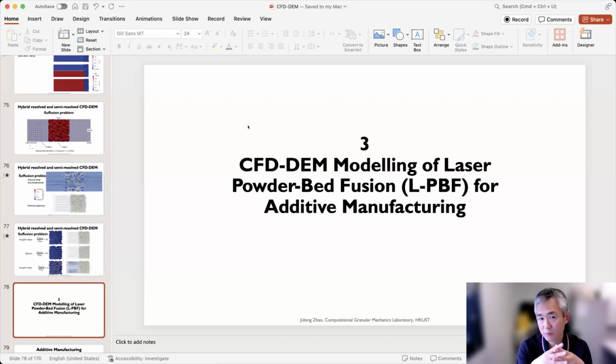You have other effects, and so that is structure response. Of course, as I mentioned at the beginning, this is a simplified way to simulate this twisted wire, and you can further develop or refine this model to capture so-called progressive failure. But of course, this is a trade-off between the resolution and the computational efficiency.